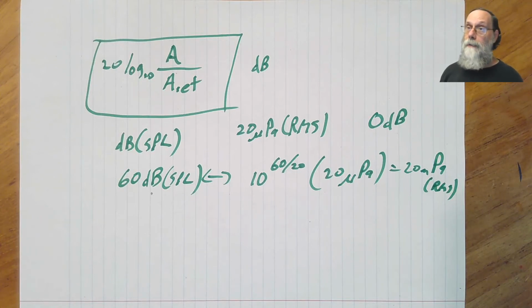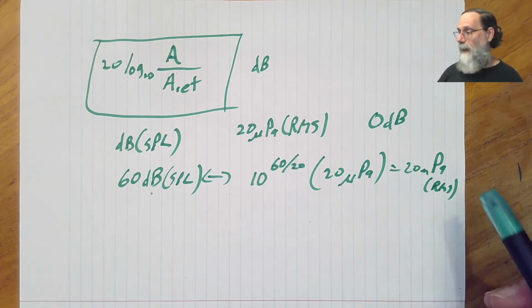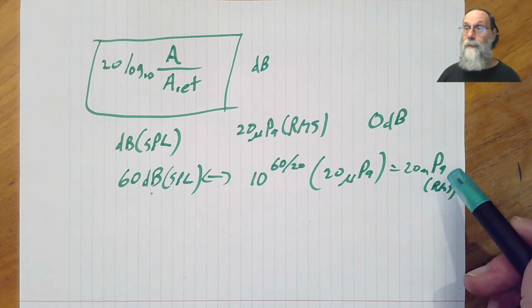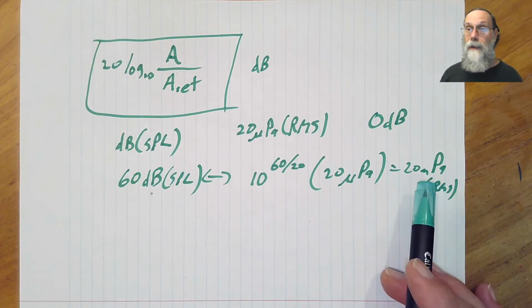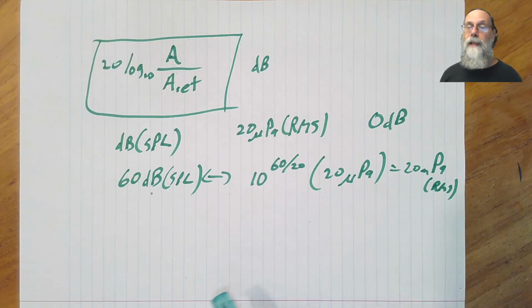That's why if you tried to use your pressure sensor as a microphone, you didn't hear anything with it, because it was sensitive to fluctuations of a few pascals, and the fluctuations from sound in the room were only on the order of 20 millipascals, way too small to be visible with the pressure sensor. That's why we have microphones, which are very sensitive to these tiny fluctuations in pressure, but which are designed to be insensitive to barometric pressure changes, which are slower and very, very much larger.